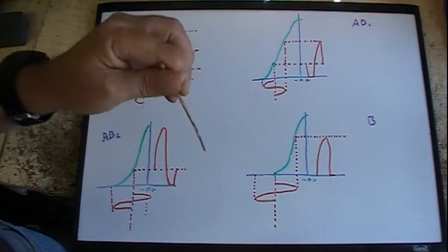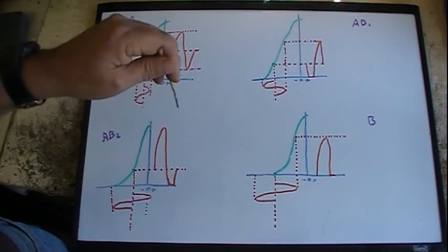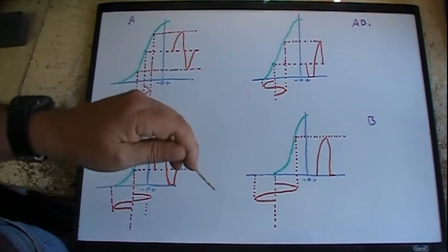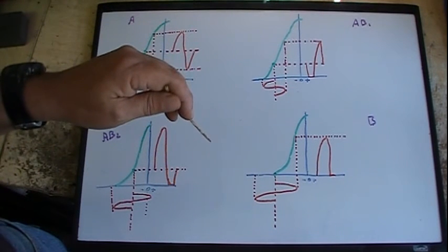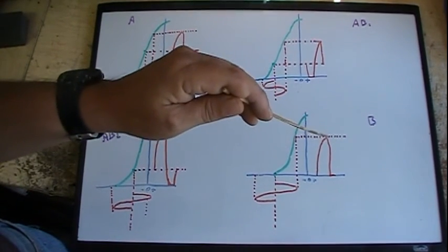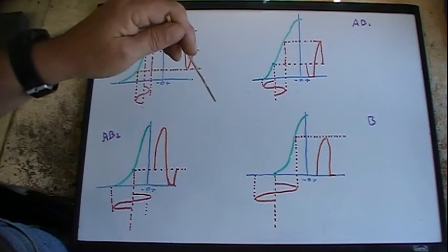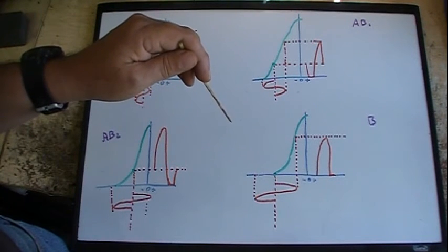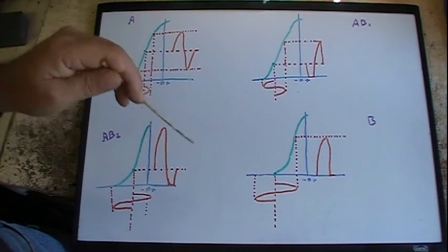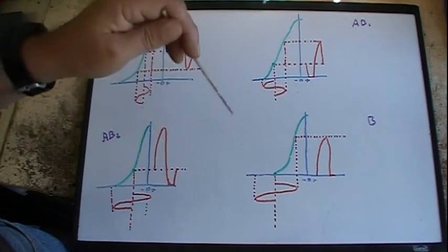Now, when I talked about that previous radio, one thing I did mention is that those only work with pentodes. You can put beam power tubes in those circuits, such as a 6V6, but all you end up with is basically a single-ended audio amplifier, because you don't really have push-pull. On beam power tubes, there's virtually no current to speak of on the screen grids, and with no current I can't get any voltage. With no voltage, I can't control the grid of the other tube, so it just kind of floats in there.